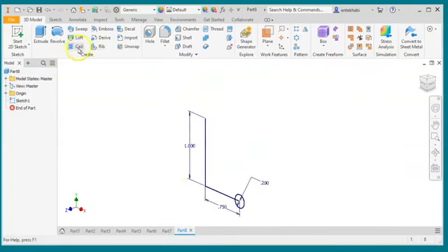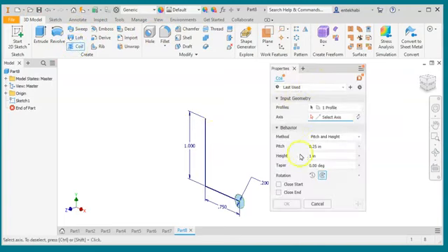Now we will apply this coil tool, which is in the modeling features. As you see, under the loft, you have this coil. Select that. Once you select, you see it automatically picks the profile for you. If it's not, then you can select the profile. But in this case, only one automatically picks. Next, we have to look for the settings under the behavior. The earlier version had a slightly different menu, but it's the same concept, in case you were working with an earlier version of Inventor.